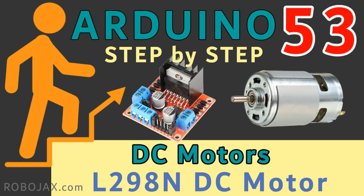Examples: A4988, DRV8825, TB6600. 3. Micro-stepping stepper motor drivers. Function: micro-stepping drivers control the stepper motor in very small increments of a full step, dividing the full step into smaller fractions, e.g., 1/2, 1/4, 1/8, or even 1/256 steps.